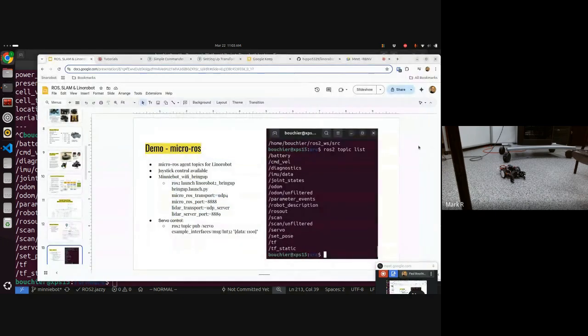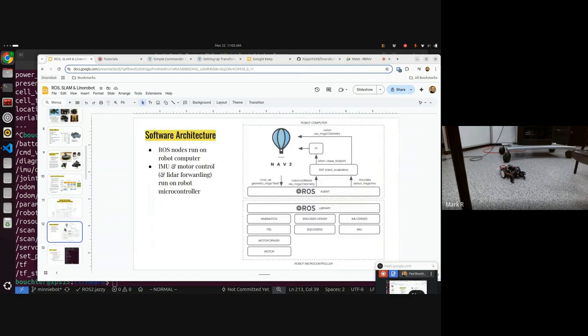So right now, what's running is the micro-ROS agent, this EKF robot localization node, the TF node that's publishing the location of the robot, and odometry is coming out of the EKF node. So it's just sitting there. That's all that's running at the moment: three or four nodes in ROS land that are getting data from the robot and ready to send data to the robot.